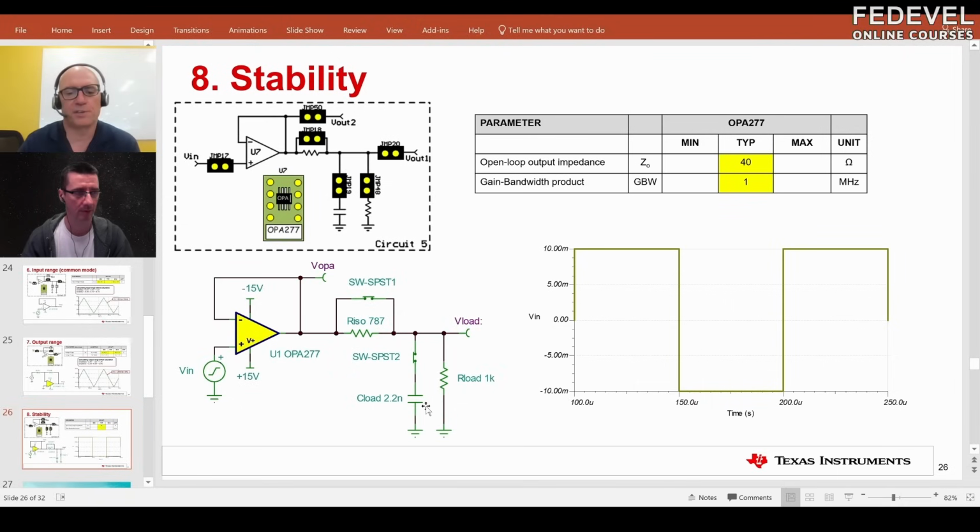We have a whole series of videos on how to stabilize amplifiers. Sometimes you do have to drive a capacitive load or an inductive load. So how do you do that? Well, there's a lot of different ways that you can make an amplifier drive that capacitor, but the very simplest is to simply put a resistor between the op amp and the capacitor, and selecting the values requires the use of some math and simulations, but we're not going to cover the details of that today.